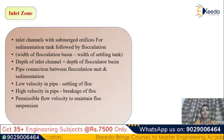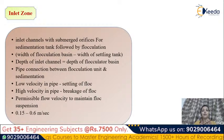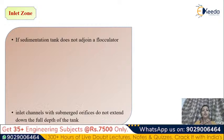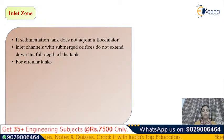The permissible flow velocity to maintain the floc in suspension is equal to 0.15 to 0.6 meter per second in case of secondary sedimentation in the coagulation and flocculation process. So the minimum velocity we are maintaining is 0.15 to 0.6 meter per second. If the sedimentation tank does not adjoin a flocculator, the inlet channel with submerged orifice does not extend down the full depth of the tank.